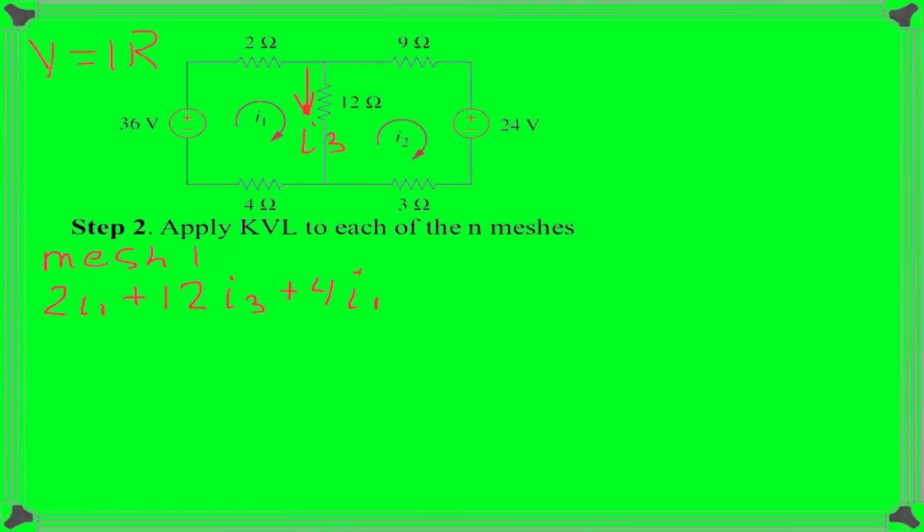We're going from minus to plus, so we're going this way from minus to plus. That means that the voltage will be assigned as negative, and we need to put minus 36 into the equation, and this is all the elements in the single loop. So we can say that everything equals 0.